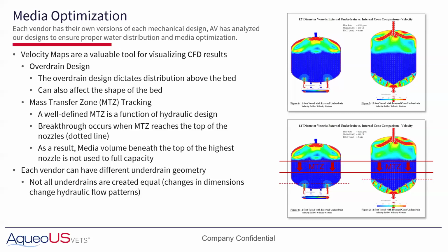There's no early warning system in PFAS. You start looking at compounds like TCE, PCE. We can sample the vessel, and we know that when we start seeing some breakthrough, we got a period of time before we're going to have to change the media out. When it comes to PFAS, because we're at 4 PPT, most of the labs are just reporting around 4 PPT. You're going to be going 0, 0, 0, and then all of a sudden you're going to be at 4. And that's why we have two vessels in series. That's why we need to optimize the flow down through the system so that we do get better performance.